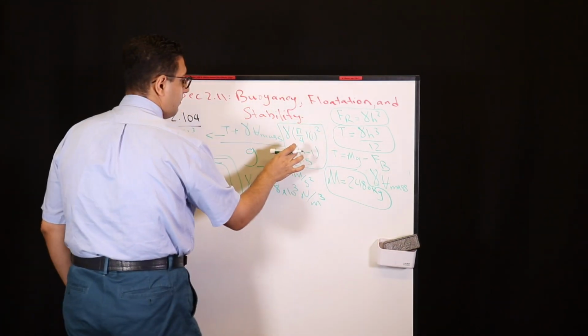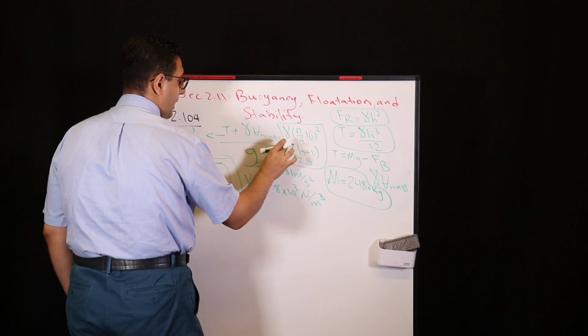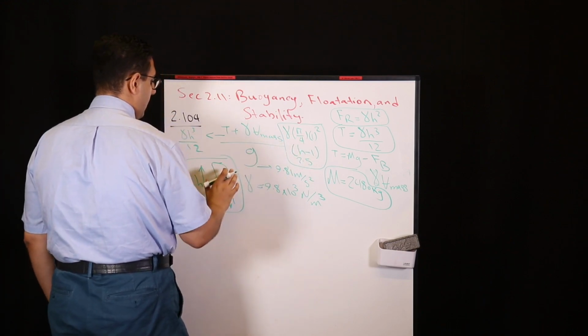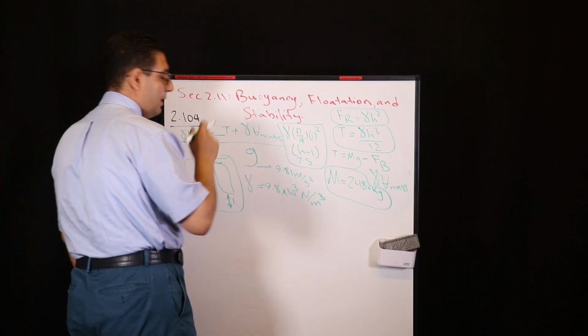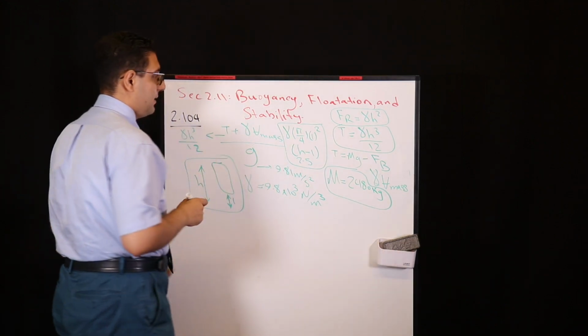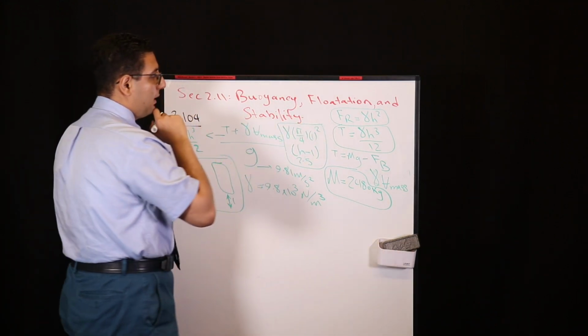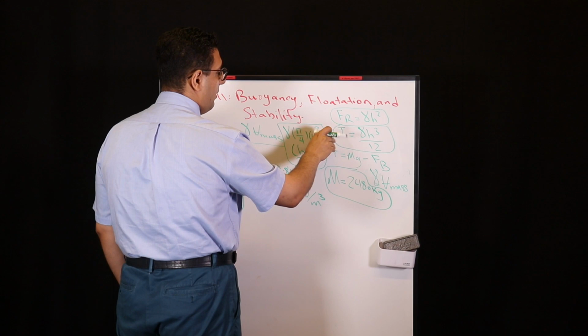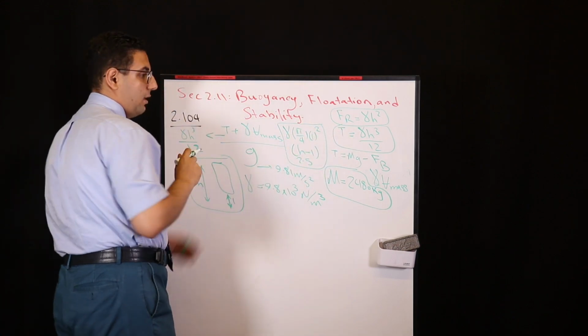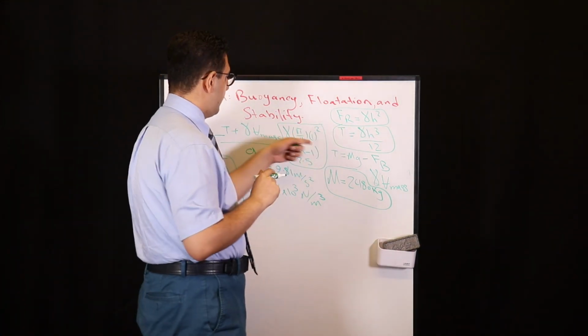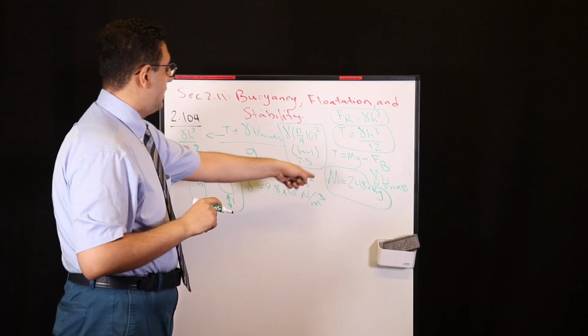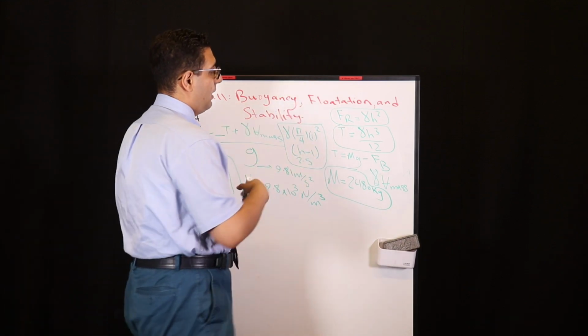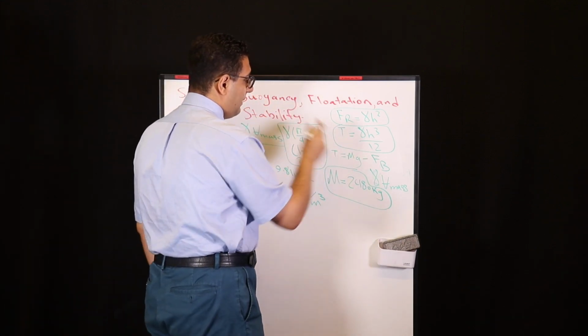So the point of this question is this distance, which is involved in the volume of the mass. We calculated the tension of the cable from the free body diagram at the left side, and then used it in this formula to find the mass of the cylinder.